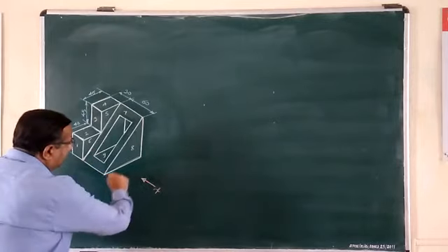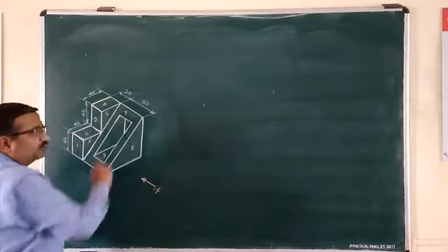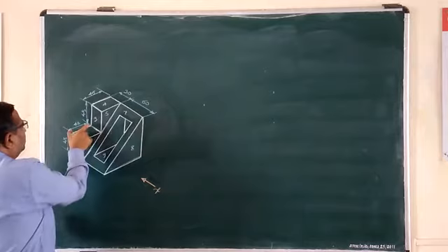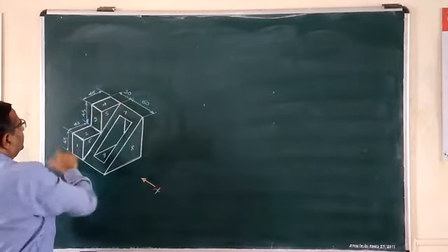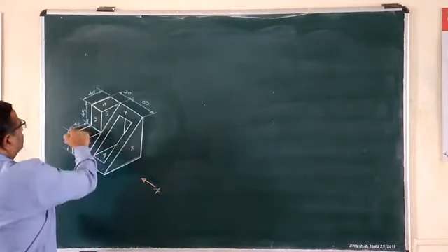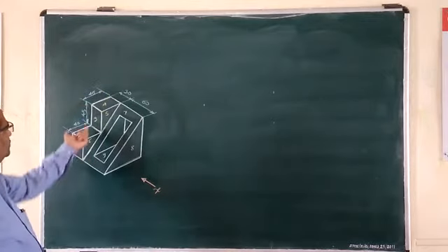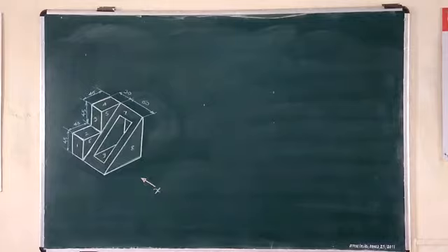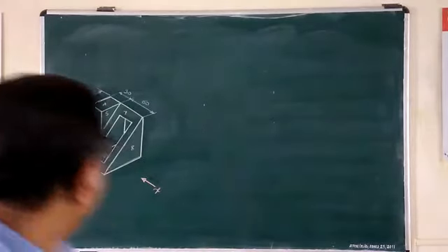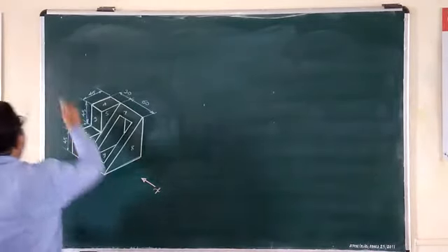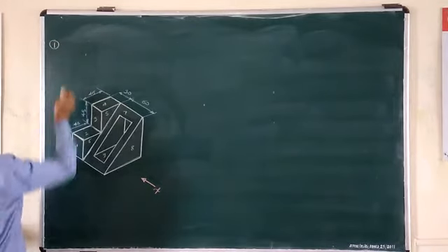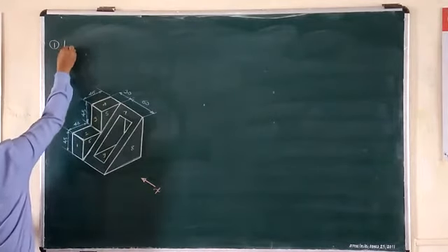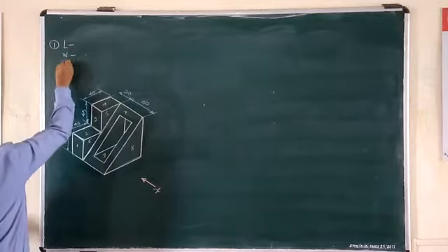Lengthwise, you have to pick the dimension lines parallel to the right 30 line. So this is one bit of 45, the next bit of 45, parallel to right 30. So 45 plus 45, you have to sum up those segments. The first point is to note down the overall maximum length, width and height of the object.